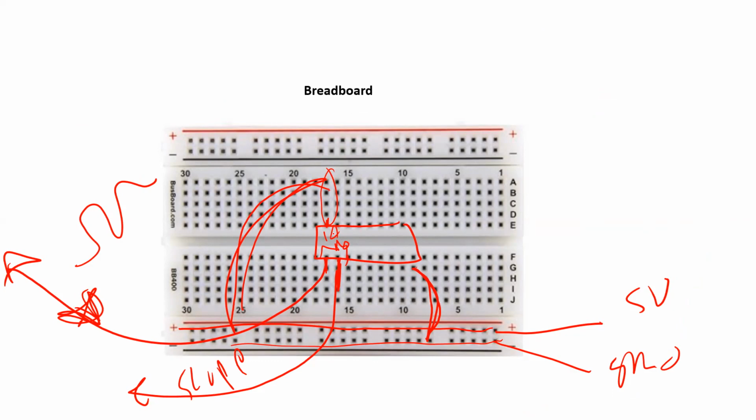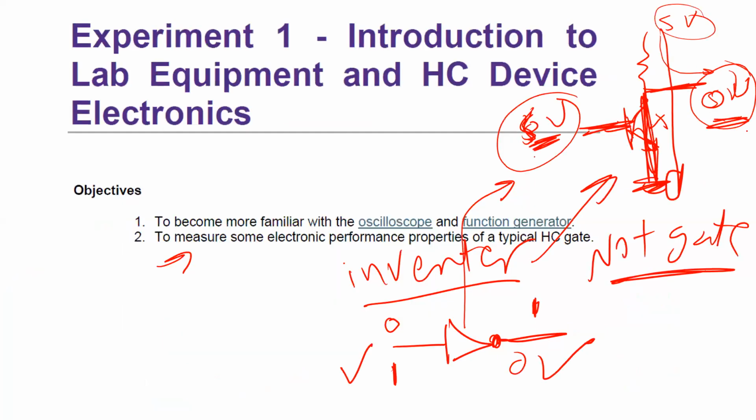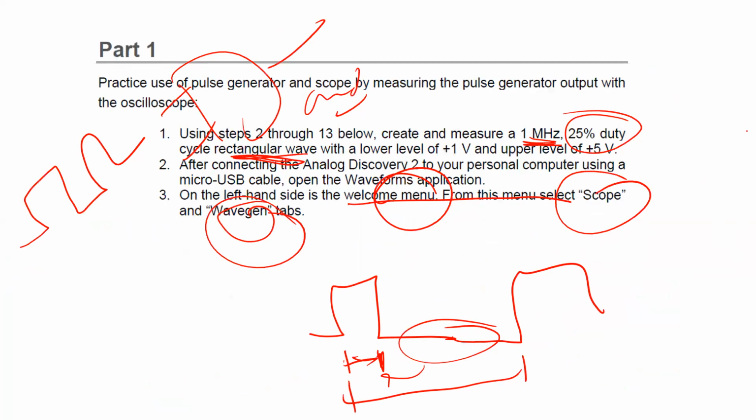By this way, I'm going to use one inverter here, but keep in mind, guys, very important, you have to make sure you connect ground and you have to connect VCC, which is 5 volt, to be able to use any inverter here. If you don't do that, none of these transistors are going to work. That's the biasing, or the voltage needed for the transistor to work.